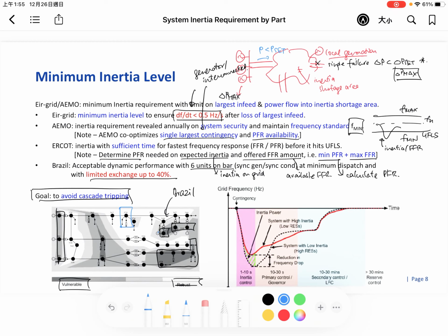The reason why it is the most vulnerable part is that it can trip, and once the generator starts, the system will take so much reactive power to build up the field of the generator and start to have some kind of generation. It means that it takes some kind of support from the grid anyway, and the scarcity will occur locally over there, and it is the weakest one in the grid anyway.